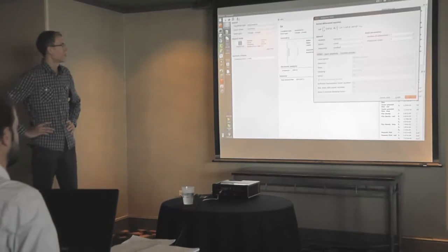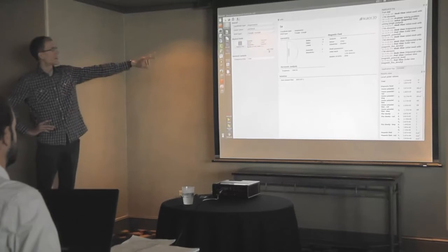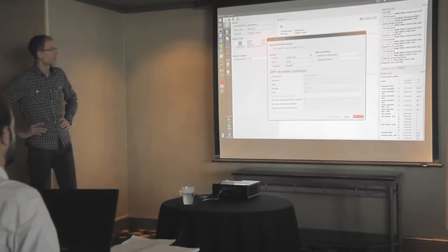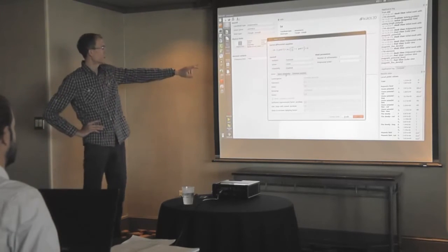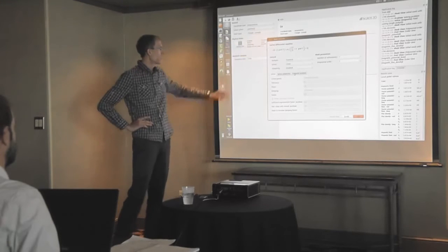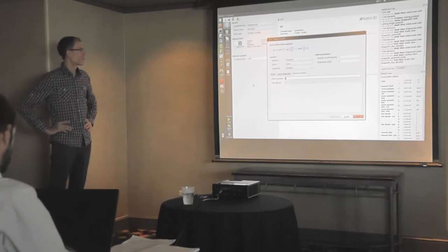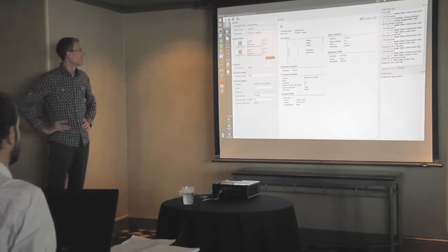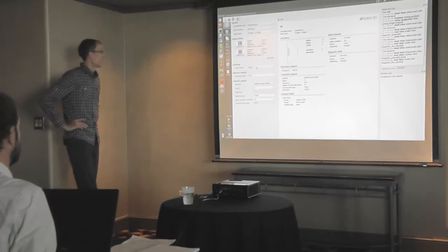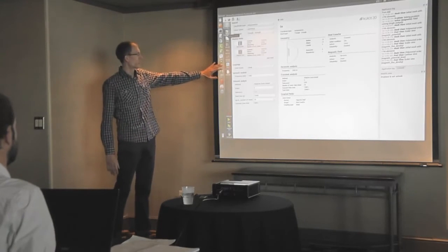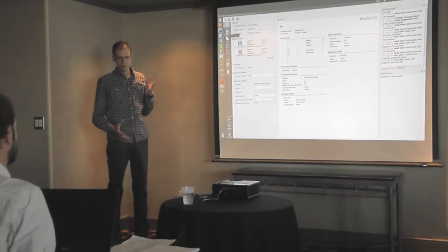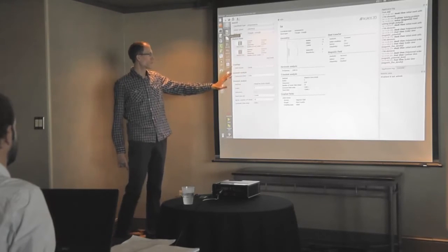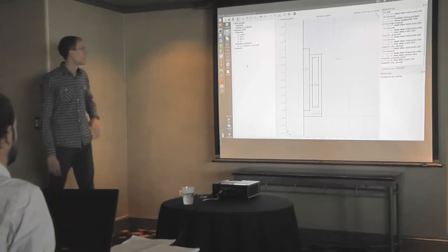Let us return to the model. So we have to add another field, which will be the heat transfer, and again specify the basic settings, like it's transient. Again, you can see the equation here, and then you have to put some initial condition. Here is the coupling, which is automatically selected. If you add magnetic and heat field, then you have this coupling. You can also, of course, switch it off, but by default it's on.